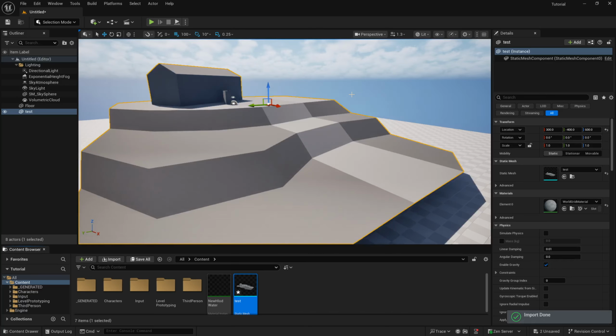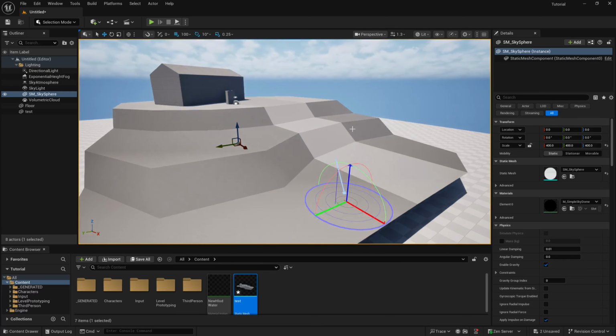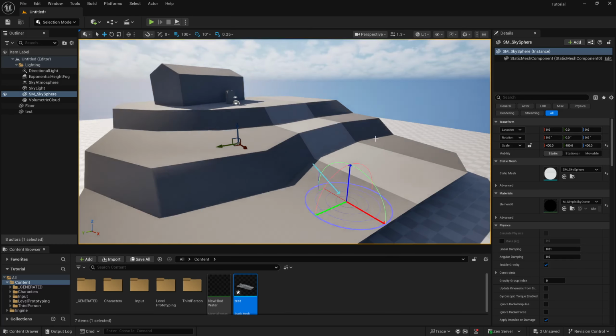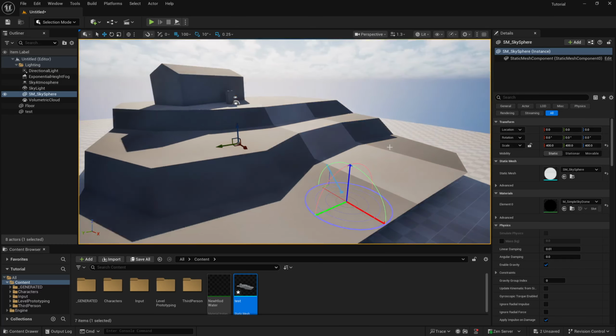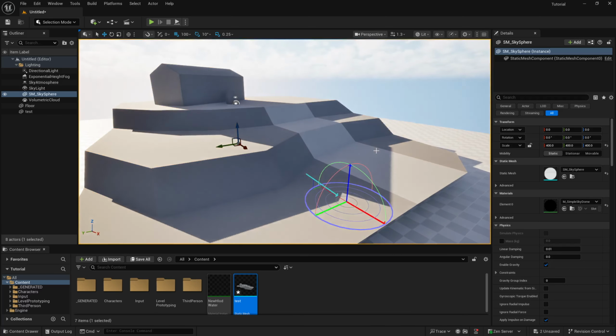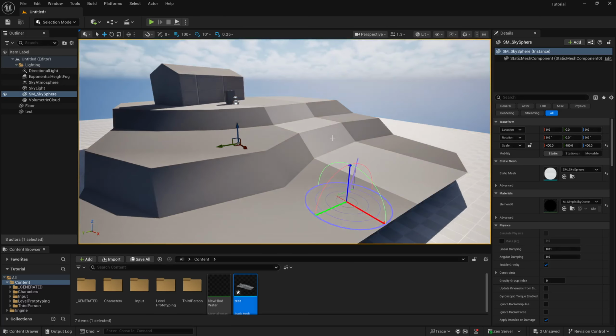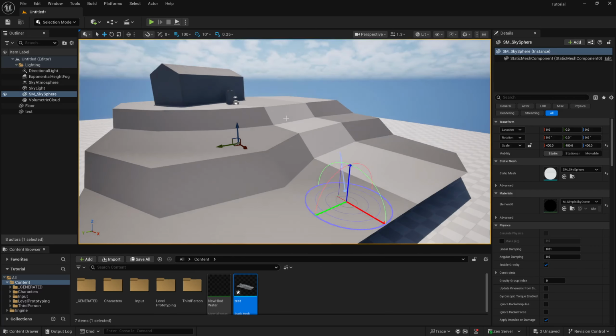And it just gives you a chance to play around not only with the static mesh, but Blender's lighting system. You can mimic what happens in game engines with Eevee or Cycles. But Control L, hold it down, you can change the light source a little bit. That's just like the sunlight. This is all you need to get really started. And I would highly recommend, if you're going to work on environment pieces, try to do them at high noon or somewhere around there at first. Because if it looks ugly here, well, the lighting does look ugly. It's very unflattering.